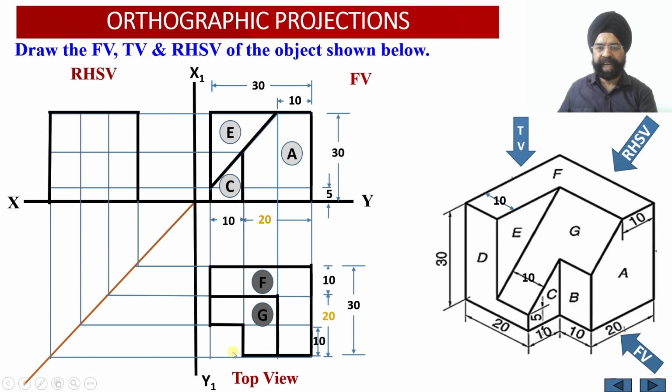So I know this cut, please check, this is the depth over here, equal to 10 millimeter. I know the height of the surface. What is the height of the surface? It is equal to this one. This I had obtained as a result of moving 10 millimeter towards the right side as I move along this particular inclined surface. So this height we had observed in the front view, and the depth is available over here.